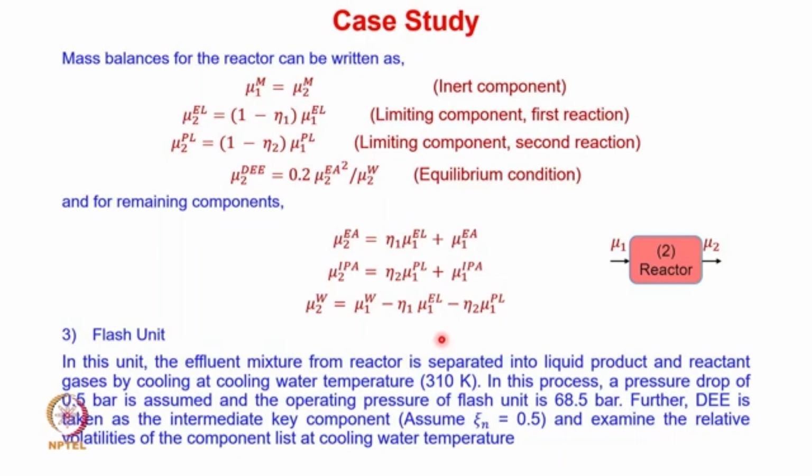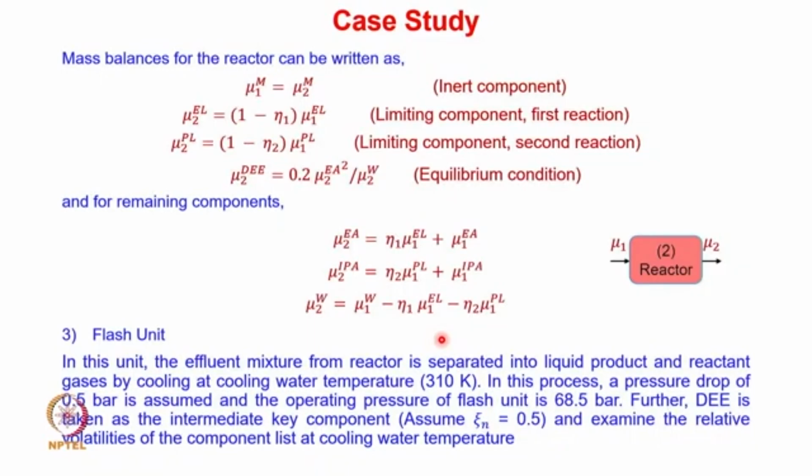Okay, so note down that when we discussed that particular flow sheet, we said that water is going to be the limiting element. Primarily, we will be using 0.6 ratio of water to ethylene, isn't it? But in this case, in order to simplify the calculation, since water is going to be recycled back, using the ethylene and propylene as limiting components simplifies the analysis significantly.